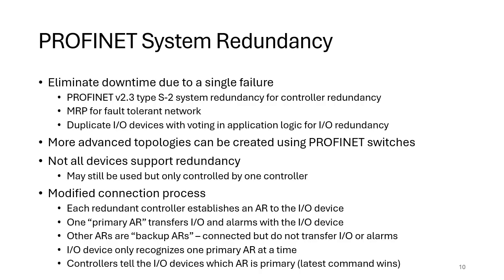However, remember now that with R2 redundancy, you've now got an additional or more complicated I/O connection. So potentially your I/O is now less reliable because you've got more complexity at the I/O level. If you want to eliminate that I/O issue, then you would implement duplicated I/O devices. Now the other thing about R2 is it does potentially survive multiple failures in a better way than S2 system redundancy does. But this is where your failure mode effect analysis comes in.